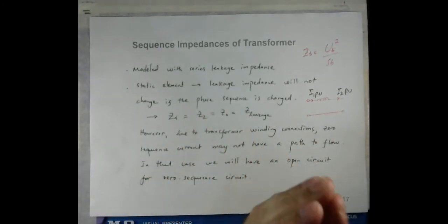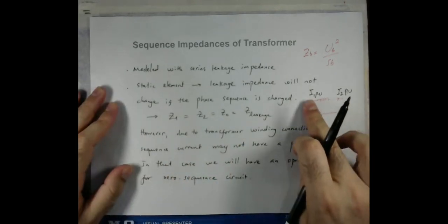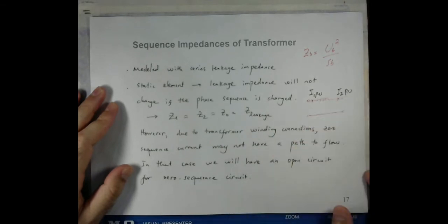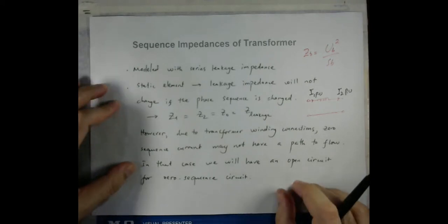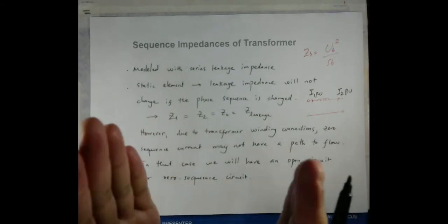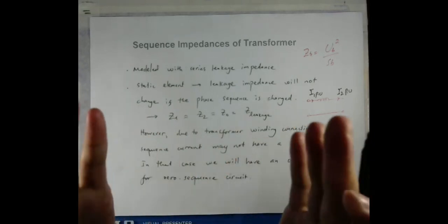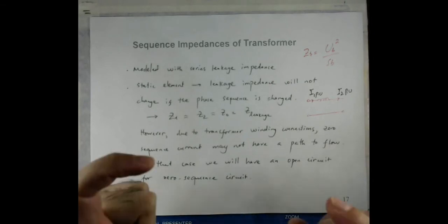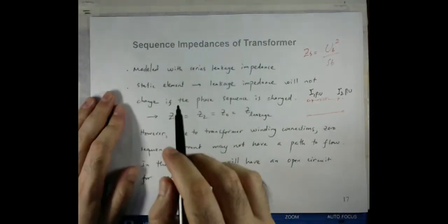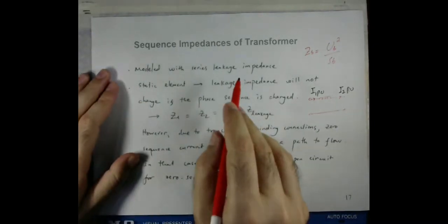So in the per unit case, the transformer windings can no more be considered, and we have the same current when we talk about per unit quantities, and also the impedance is the same. That's why on the nameplate, the transformer impedances are usually shown as one value, either in percentage or in per unit. So we will only consider the leakage impedance.